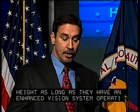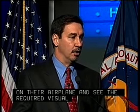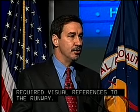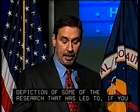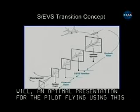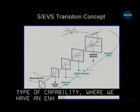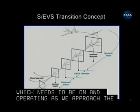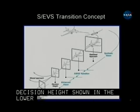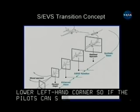So what we're showing here is a depiction of some of the research that has led to, if you will, an optimal presentation for the pilot flying using this type of capability, where we have an enhanced vision system which needs to be on and operating as we approach the decision height, shown there in the lower left-hand corner, so that if the pilots can see the required visual references, they can continue below that decision height and then safely land on the runway.